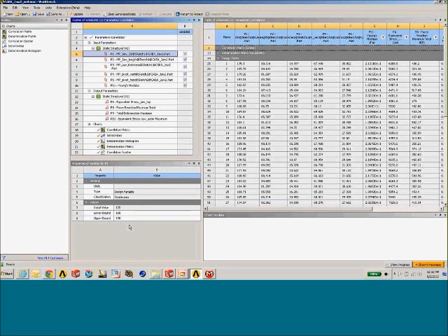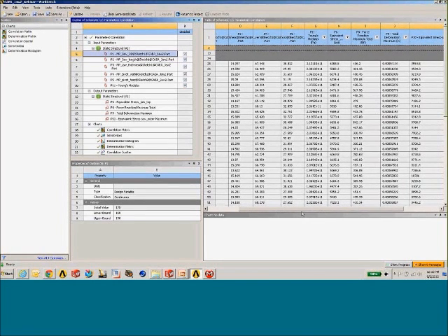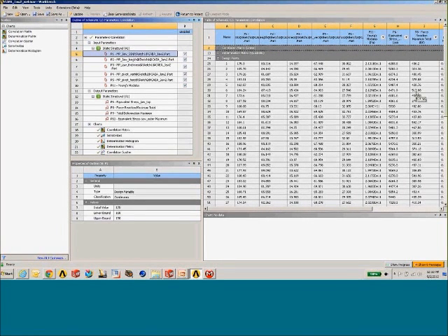One thing that you can do is go back to the CAD tool, and you can evaluate your upper or lower bounds of your parameters to make sure that they regenerate. But if you want to automate that process to a degree, you can simply set up the correlation tool, set up your expected ranges, and kick off an evaluation of the correlation points. What the Workbench environment will do is sweep through the correlation points, and if it finds one that does not regenerate, it'll give you a regeneration error for that point and move on to the next one.